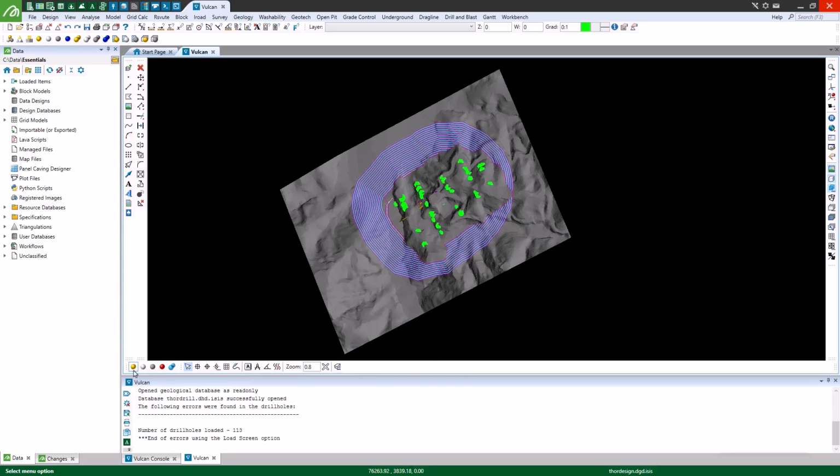The Windows visibility spheres are great because you can use them while creating design data. If you are digitizing a shape and something blocks your view, you can use the visibility spheres to hide that object without exiting design mode. You can press and hold the Shift key to quickly apply a Windows visibility operation to an entire design layer.